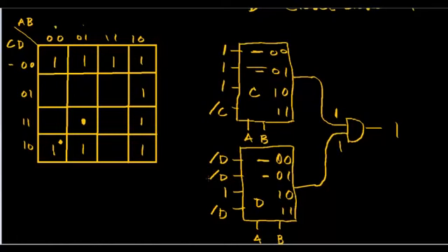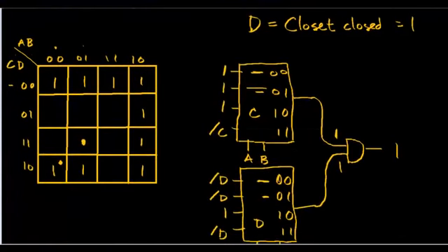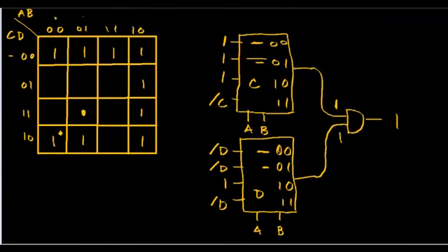Okay, so in summation, we took a real-life problem, wrote it down into terms, created a minimized logical equation, plotted that equation onto a K-map, then used the K-map to design a circuit using a real 74153 IC chip.